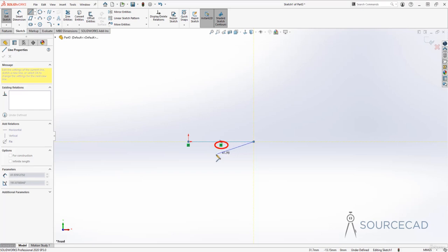Not only that, we also have a new constraint called coincident. Now that constraint will keep this line connected at the origin. So since we started with the origin, SolidWorks will ensure that it remains connected at that point. Now I've started the line. I'll click on another point here. Now here what I see is length, so I'll just click again, then again randomly.